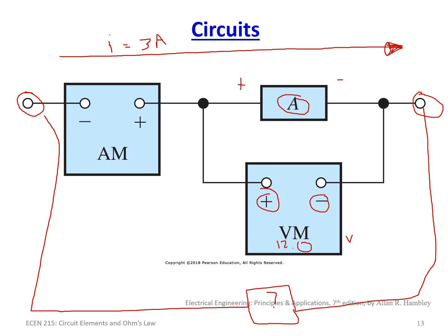One thing we can immediately tell is, if I asked you how much power was running through this, what would your answer be? It'd be 36 watts, because 3 amps times 12 volts. So is the 36 watts being absorbed, or is it being generated? As we learned earlier, if current is going into the positive terminal and leaving out the negative terminal, then it's being absorbed.